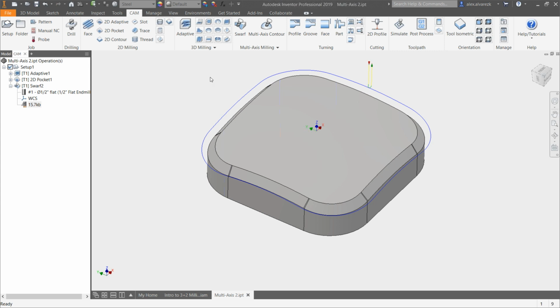Right, because I'm assuming if you use a ball end mill there, it would just go in circles, or I guess squares, around that thing until it got to the bottom. Exactly. You'd have to pass everything 3, 4, 5, 6 times, depending on the step over, right? In this case, it looks like just once. Again, you can make it 2 times if it was removing a little bit too much material. But that's still going to be much faster than having that small step over go across that bevel there.